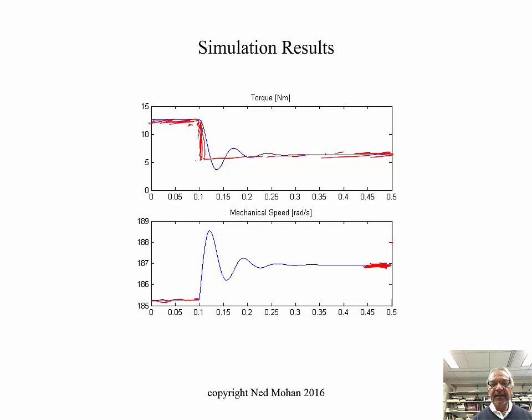So imagine that this load torque disturbance occurs, but you want to keep the speed constant. See, speed does not remain constant here. It was here in steady state before the load disturbance, and then it goes to steady state over here. These are two different values. But you can imagine a process where even when a load torque disturbance occurs, you want to keep the speed constant. Let's say that's an example. That's what you want to do. Well, you want to do what is called vector control.